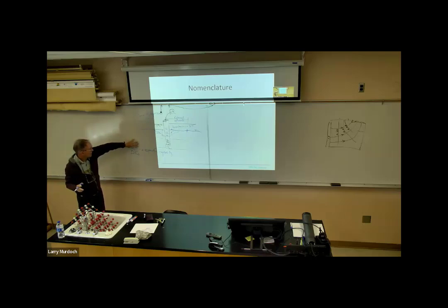We're going to be interested in how rapidly we can pump water out of the well. That'll be important. But the harder we pump it, the higher this is, the more drawdown that we're going to cause. And these two are related in this ratio. At steady state anyway, this ratio is a constant. So if we double the flow rate, we'll double the drawdown.